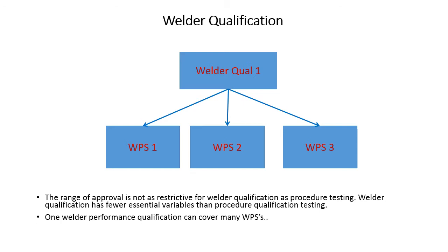Well, the welder, he's just got to qualify on F6. So F6 is filler metal. And the filler metal is the form that the filler metal comes in. So whether it's carbon steel, stainless steel, they all fit under the F6 category. So he's qualified. Shielding gas, the welder doesn't have to, he can weld with any shielding gas with the gas tungsten arc welding process. Whatever the shielding gas is, he can use it.